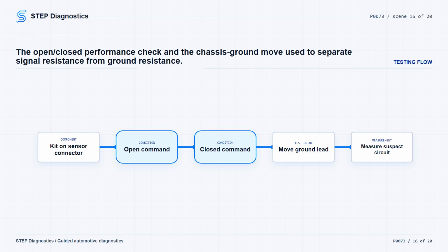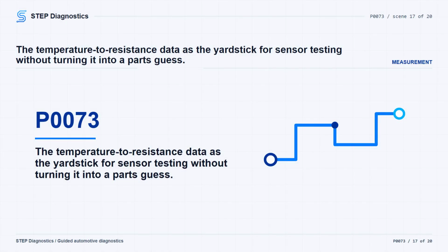The chart points include -40 degrees C, -40 degrees F at 345.26 k ohms as the lowest possible temperature reading, -10 degrees C, 14 degrees F at 53.38 k ohms as a logical temperature value, -5 degrees C, 23 degrees F at 40.89 k ohms, 0 degrees C, 32 degrees F at 31.56 k ohms, 5 degrees C, 41 degrees F at 24.55 k ohms, 10 degrees C, 50 degrees F at 19.24 k ohms, 15 degrees C, 59 degrees F at 15.22 k ohms,